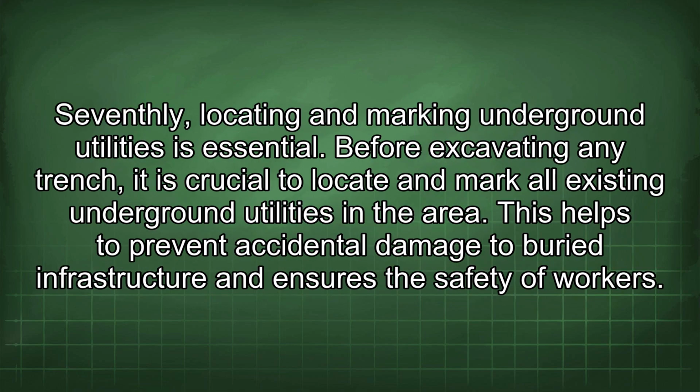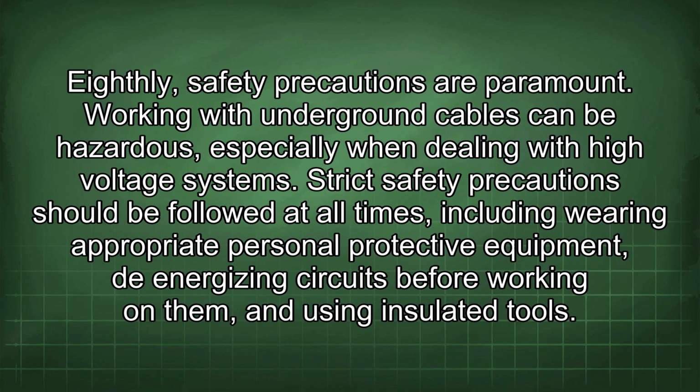Seventhly, locating and marking underground utilities is essential. Before excavating any trench, it is crucial to locate and mark all existing underground utilities in the area. This helps to prevent accidental damage to buried infrastructure and ensures the safety of workers. Eighthly, safety precautions are paramount.